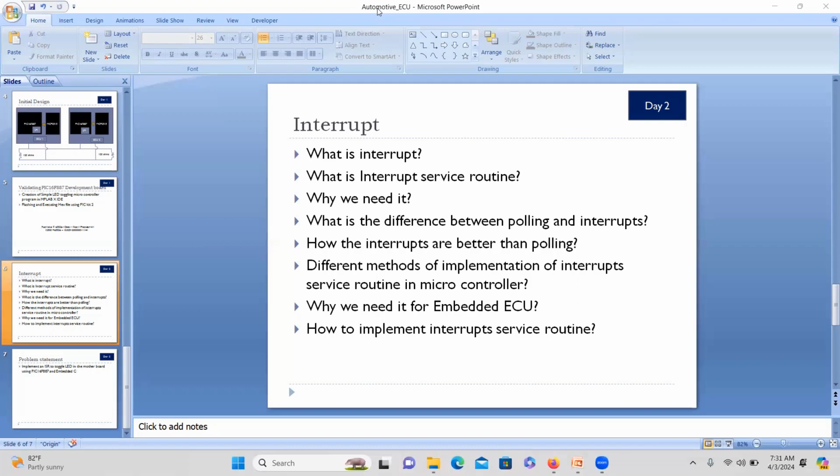This is very much needed in the automotive industry because upon receiving a CAN packet, you may do some things. Upon changing a signal in the CAN bus, you may have to execute some piece of code. These are very common in the automotive industry. So the automotive ECU is going to respond to these different interrupts, and it will also have its own schedule to execute.